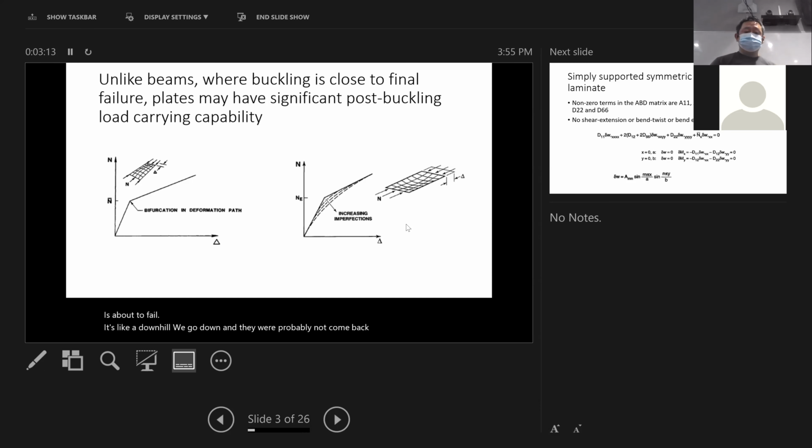When a plate buckles, you see this load displacement response with a knee. There's a knee behavior when you load the structure. In this case, it's a plate under compression. All sides are simply supported. You see suddenly a knee happen. Basically, your stiffness changes. Your structure becomes softened a little bit. It bends. You keep loading. It actually keeps carrying load.